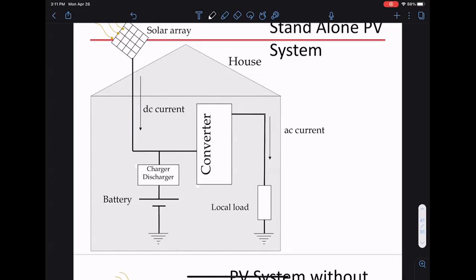Right. This kind of conversion loss, or high loss, is what you would typically see in data centers. The way data centers work even right now is you have a battery. You need to charge a battery in your data center, so you need to convert whatever energy you have, either from the grid or from solar, to DC. You charge your battery because that's your backup.